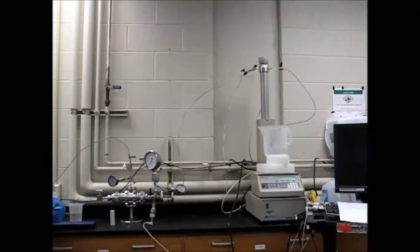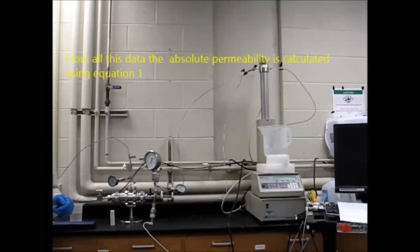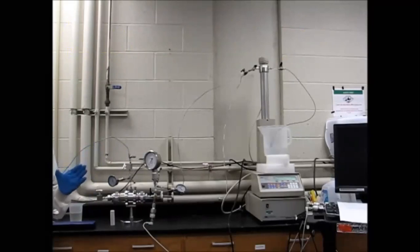Three different flow rates, 1 milliliter per minute, 2 milliliter per minute, and 3 milliliter per minute, were applied by using the ESCO pump, and the stabilized pressure is determined each time by using the pressure gauges here. From all these data, the absolute permeability is calculated using equation number 1 in your manual, which is basically Darcy's equation. Q is equal to K multiplied by A multiplied by delta P divided by mu multiplied by L.